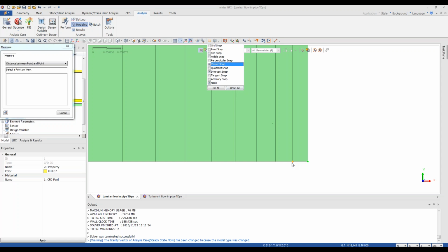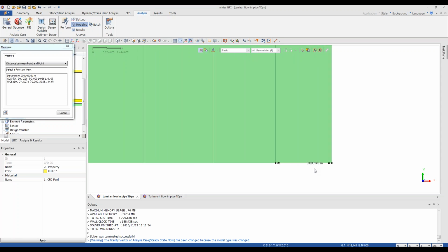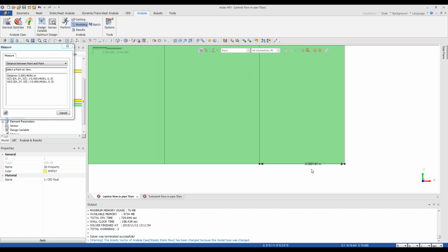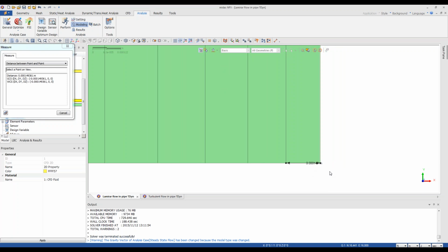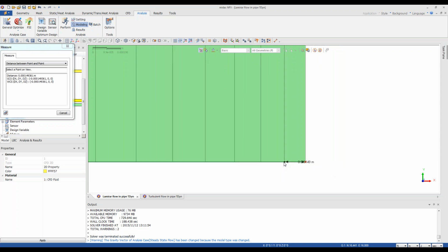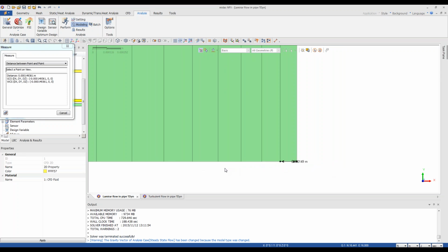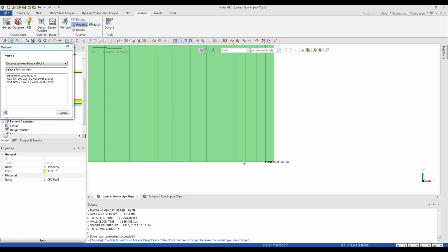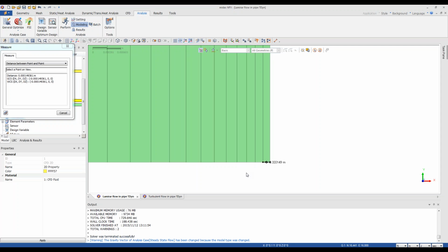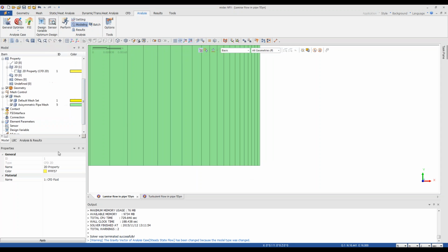If we snap to this, so it's even less as our condition which we've got from the Excel file. Of course, the ratio between the nodes is also important if we decide to use this method. So it should be almost 1 to 1.2. So this is not like some kind of magic number, but you have to know that the increasing ratio should be very, very low. So all of those elements which are standing next to each other should have the same size.